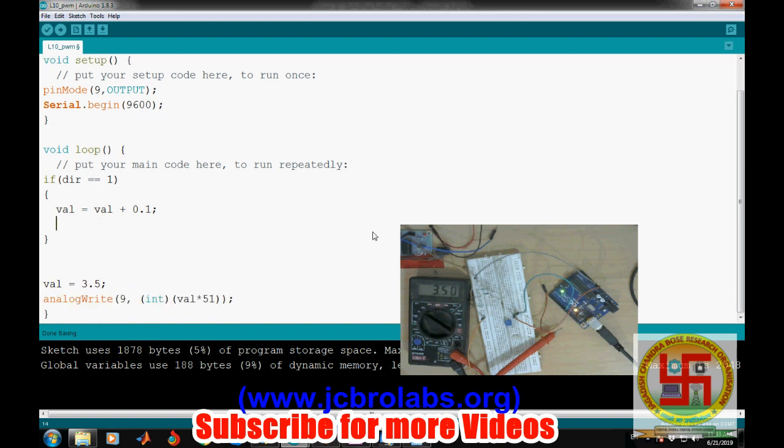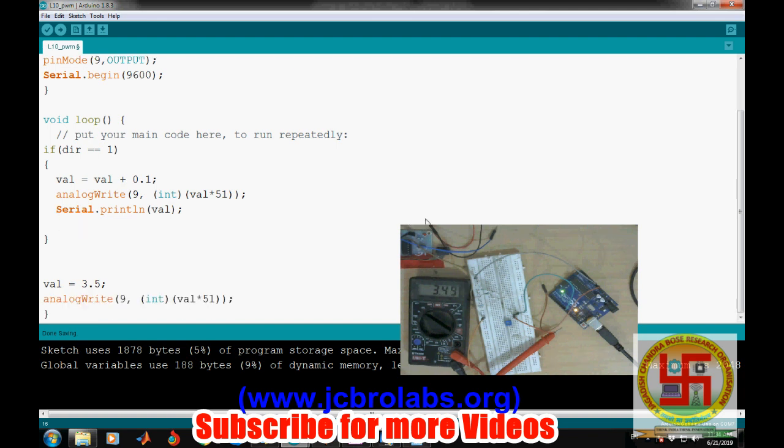Now we'll write this value. So analog write of 9 comma, again it has to be integer type, val into 51, and then we will send the same to the serial monitor, Serial.println val, where we will be able to see what is the value. And then now if this, because once it reaches to 5, right, we have to change the direction. After 5 it should be decreasing.